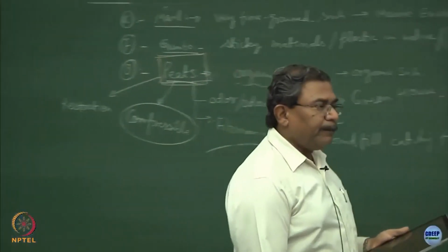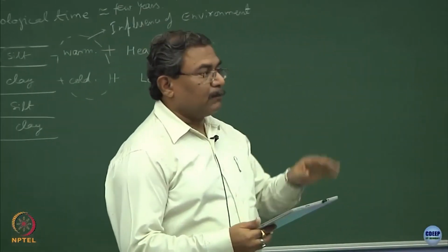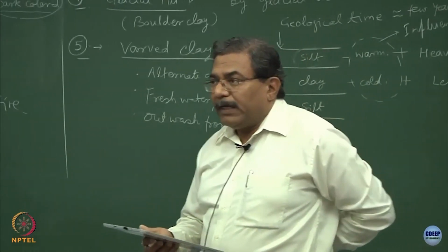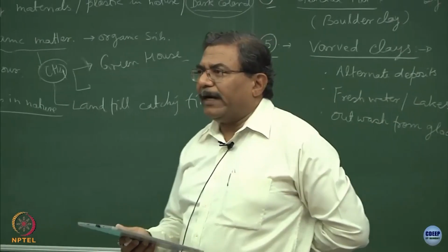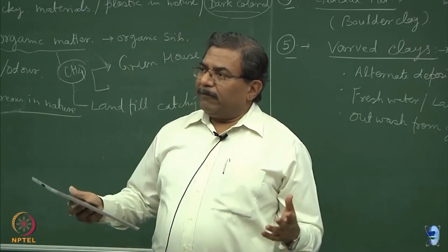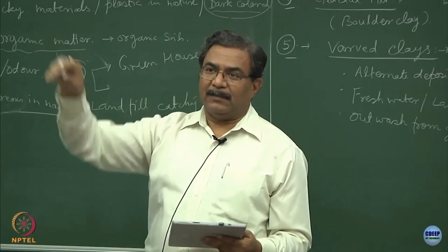I think this is a UNDP program also, where they are trying to safeguard the cities and the countries which are mostly located on peat deposits. Now, one of the ways of doing this could be, I am just giving a very vague idea, do not quote me tomorrow anywhere, alright. What would be the vaguest idea to stabilize these type of deposits? Cut off the supply of oxygen.